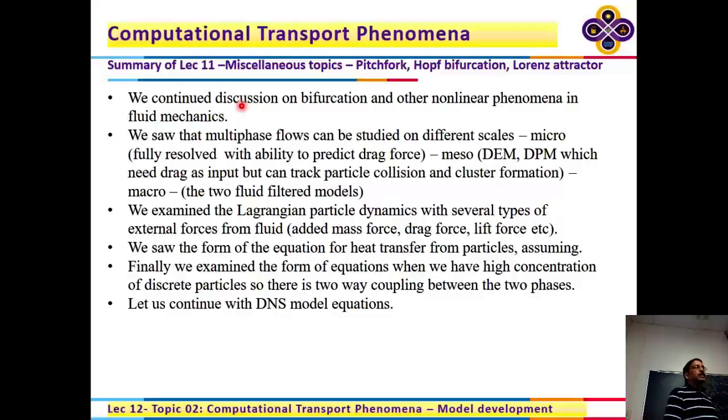So this is the R momentum equation that tells you what the pressure is in the radial direction. If you compute it and put it into COMSOL, then it's already satisfied, right? If you take this velocity field, plug it in here, integrate that, and give that pressure field as the initial condition, your initial condition already satisfies this. COMSOL is not doing any work to find this pressure field, right? But you're saying that is the only way that it gives you the correct pressure field.